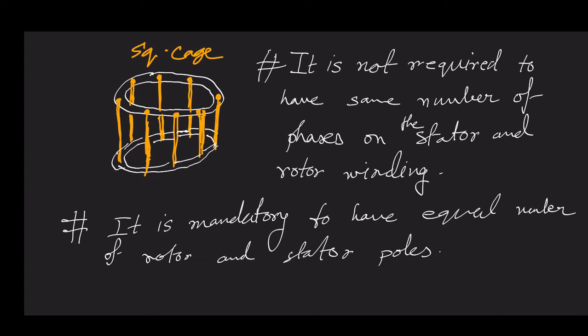This is for a single excited system, where you are producing magnetic lines of force only through your stator or through your rotor, and the other side, either the stator or the rotor, is relaxed. There is no supply on the other side, but the iron structure or the reluctance path is not even, and the flux lines are trying to stretch in such a way that they get the minimum reluctance path, and that generates a torque.